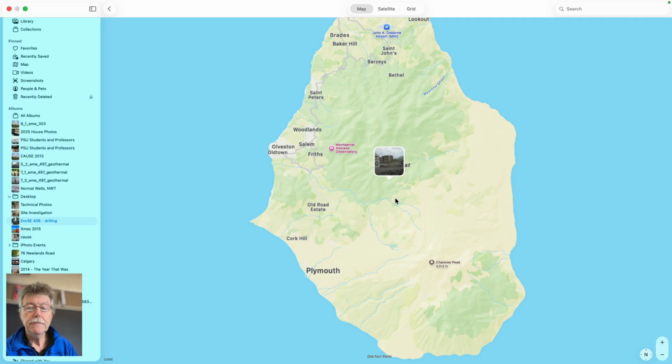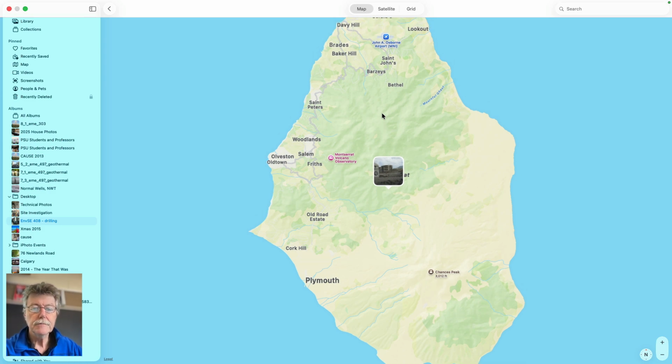And so the idea was that if you have something like a magma chamber 5 kilometers underneath this hill or 12 kilometers deep, you can measure the displacements at these points if you have boreholes that are deep enough so it's not completely swamped by surface noise. So you get a very clean signal because it's 200 meters deep. And the instruments are very precise. You can measure strains, changes in volume relative to some baseline, of nanostrains. So 10 to the minus 9 meters per meter. So very small strains.